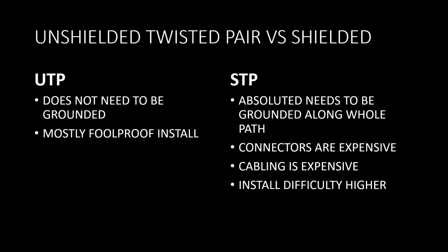And you've got the potential of, if you do it wrong, like if it's not all the way grounded, then all that extra metal in the cabling can potentially induce noise from outside because it's not grounded. So it's like a giant antenna wrapping around your cabling. So unless it's grounded, it doesn't actually provide shielding. It does the opposite and makes everything worse.